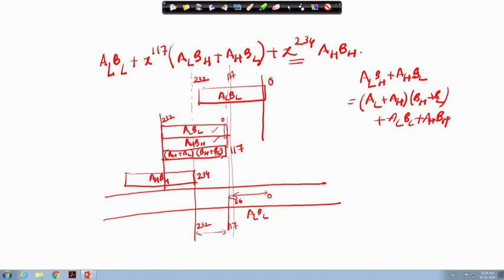Okay. The 233rd bit is something which is interesting, because it comes in between. When you are doing this addition, you have got 4 parts, this part, this, this and this. But for only 1 bit position, that means the 233rd bit position, you are only adding this, this and this. So there are 3 bits which you are adding. Okay. So that gives you the 233rd bit.